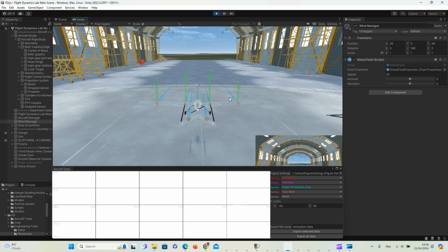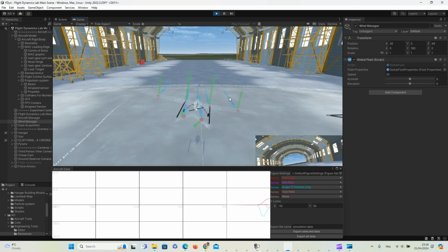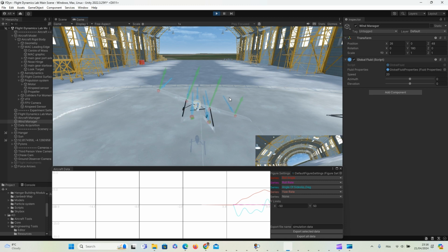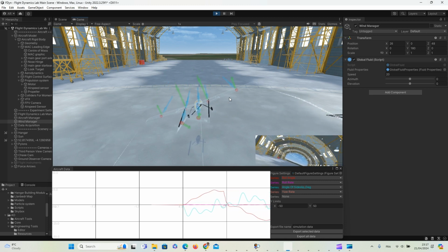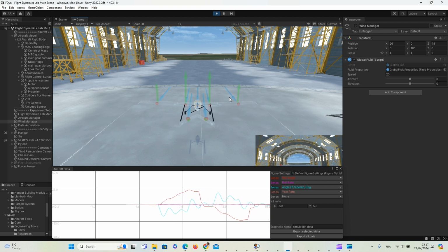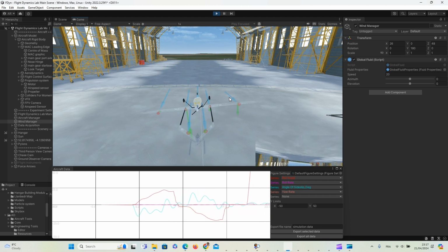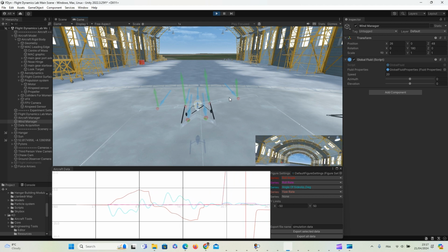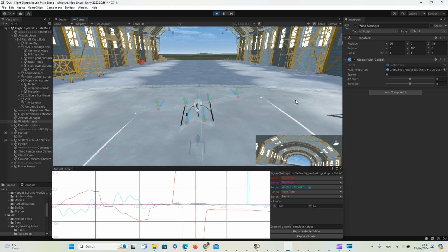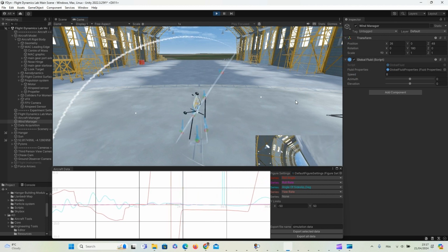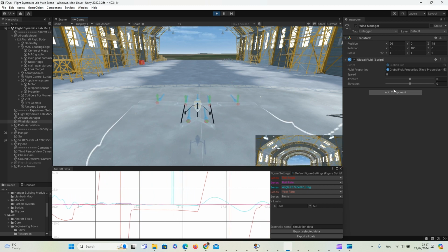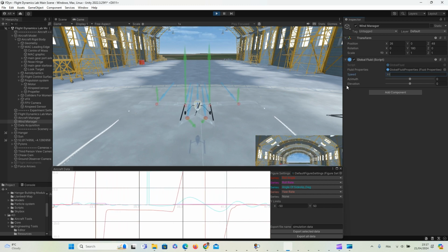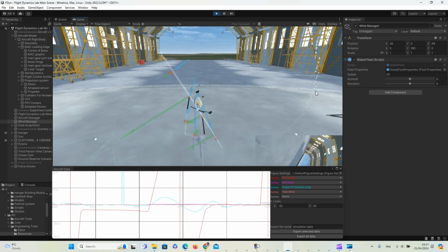The lateral dynamic response of the aircraft shows that the deflection of rudder pedals is providing the correct side slip angles. Likewise, the deflection of the ailerons is providing the correct roll directions, as demonstrated here. And varying the flight speed would also change the response of the aircraft's lateral motion, so slowing it down obviously makes the controls much less responsive, whereas speeding up the flight speed would make the lateral controls much more responsive.